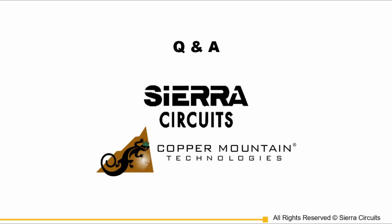De-embedding, on the other hand, gives you a great response. If you're trying to hit an open or a short or whatever you're actually looking at for your calibration, it'll put you right on a short or right on the open, and there will be no arc, no little squigglies. It'll do a great job. To do de-embedding properly, you need to make a two-point measurement of the thing that you're de-embedding. Or if you can only get at it from one side, you need to use the automatic fixture removal program, which we also offer with our VNAs.